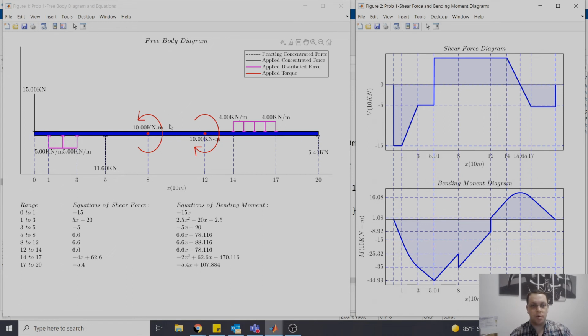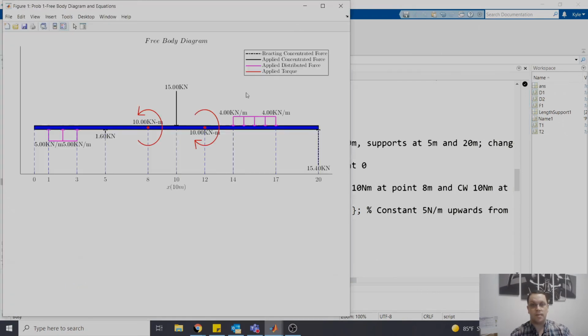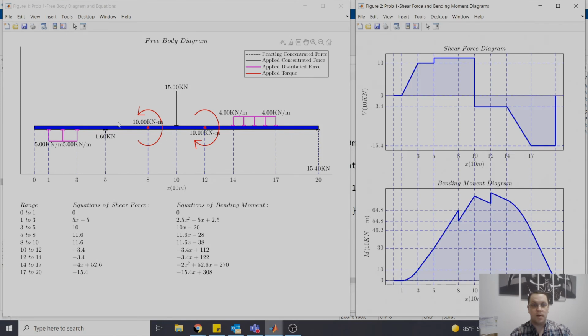What happens if you put the point load dead center? What does that do? Well, let's take a look. So if you put the point load at the dead center and you say at 10, what do we get? So now we see this part has a very, very small overall load, but our bending moments now are very high in comparison, so significantly higher than they were for the other cases.